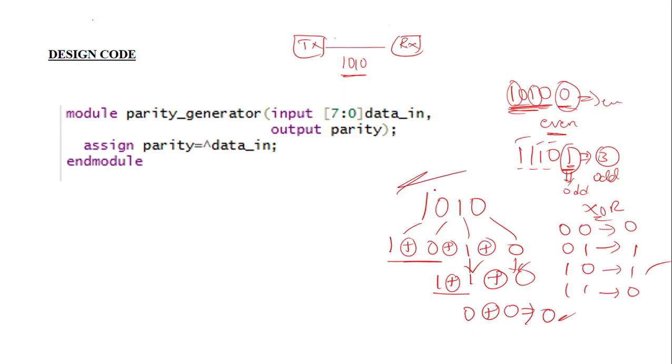For writing Verilog code we use this second process. Now we are going to write the parity generator in code, to find whether the parity is even parity or odd parity. We have to start the Verilog code with module and end with endmodule. We can name the module parity_generator. That is our module name.